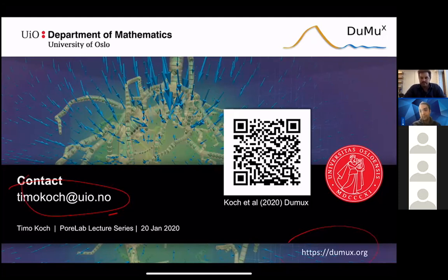Hello, this is Björn Hafschall. I have a question about your equations on the flow between the vessel and the porous medium. I saw you use the pressure difference as the driving force. If you have fluids that are mixtures of different components, then I guess you should use the full chemical potential, including the composition difference, also in that equation.